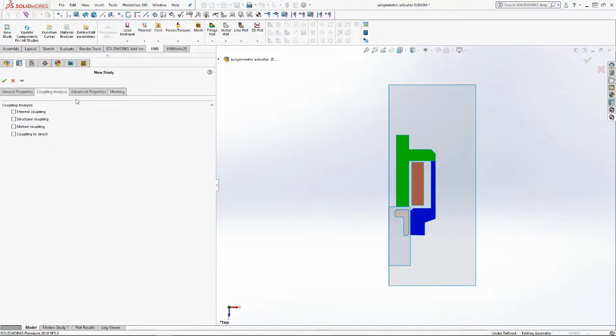So we have this meshing tab, with 2 options. We have manual meshing, so the user has the responsibility to define the mesh. He can define mesh controls, he can play with the settings, and so on. And we have the second option, which is called adaptive meshing.